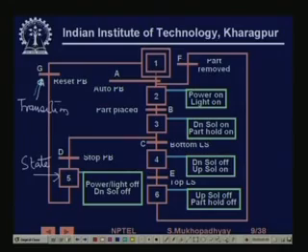You see that the double square means that it is the initial state. Initially, if the auto push button is pressed, transition A gets activated and takes the system from state 1 to state 2. This is the transition condition. You can have much more complicated conditions, but in this case we have very simple ones.